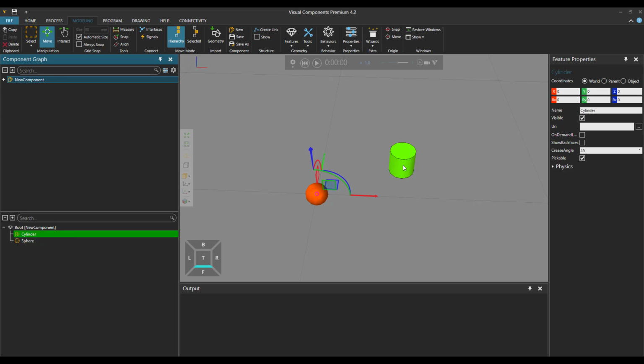So the feature keeps its offset while retaining its location in the 3D world. So when you collapse a feature that has an offset from the origin of the component itself, the collapse resets its position matrix and keeps the offset of the feature. And it doesn't really matter in what order you do that.